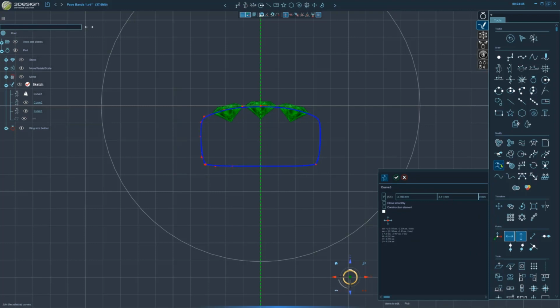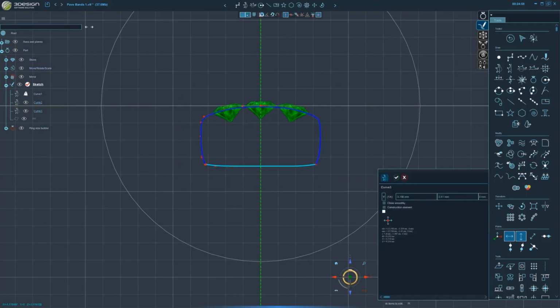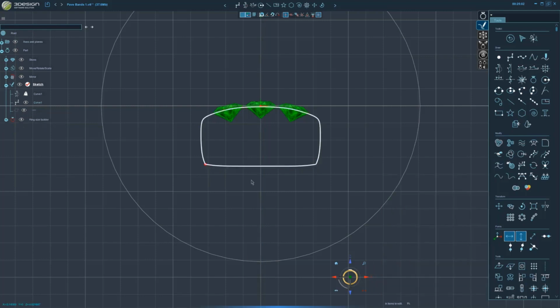You can do a join curves by selecting them, or you can use auto connect, but I don't want to do an auto connect. It might get in the way because we've got that third curve back behind there. So in this case, I want to select exactly the two curves that I want to join and join them manually, just in case. Now I've got that sharp point in the start point area here, and then the one where it joined at this corner here. So sometimes we do want those sharp points. That's going to create those edges for us.